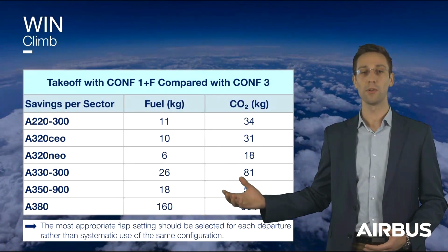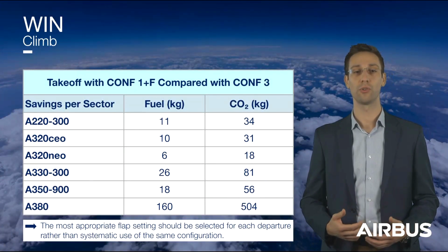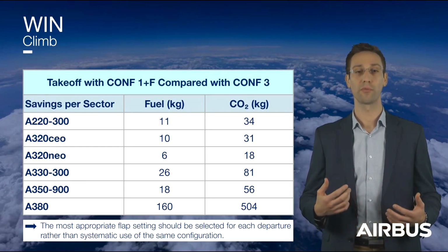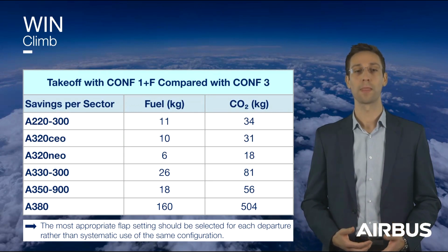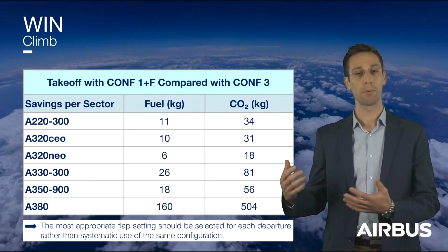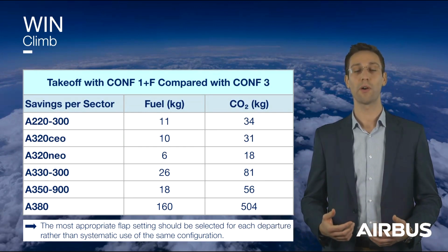In this table, you can see the fuel saving and CO2 emission reduction done with a conf 1+F instead of conf 3 set for takeoff. Keep in mind that the right balance between performance, noise, and fuel consumption should be found during the selection of the takeoff configuration.